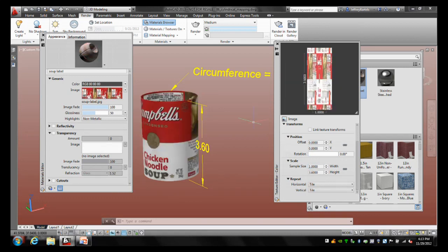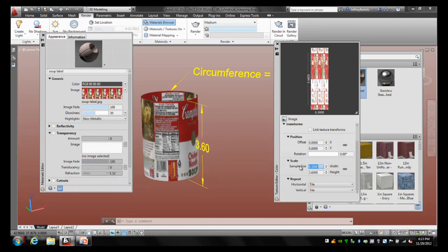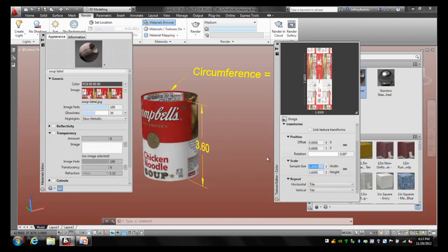What that means is essentially 1 time around, seam to seam. So you've got 1 image all the way around. Knowing that if we were to set this to something like 0.5, then we would see 2 labels going around. Okay? So when you're doing cylindrical mapping, the width, height's what you would expect, width's always going to be 1. Okay?